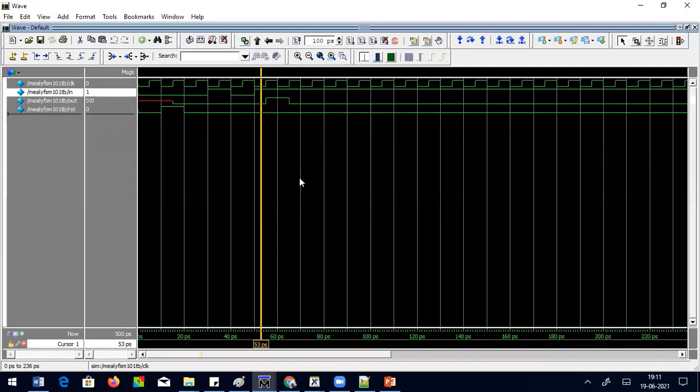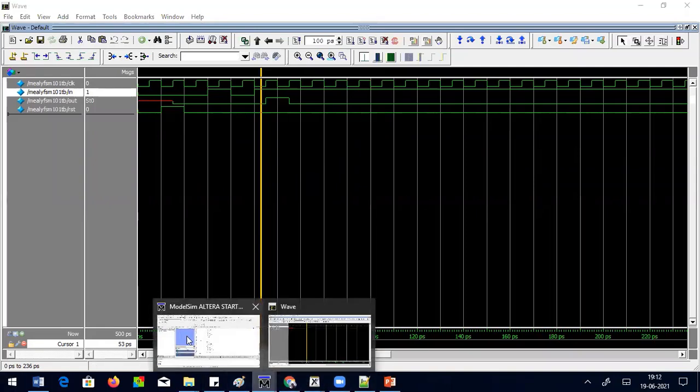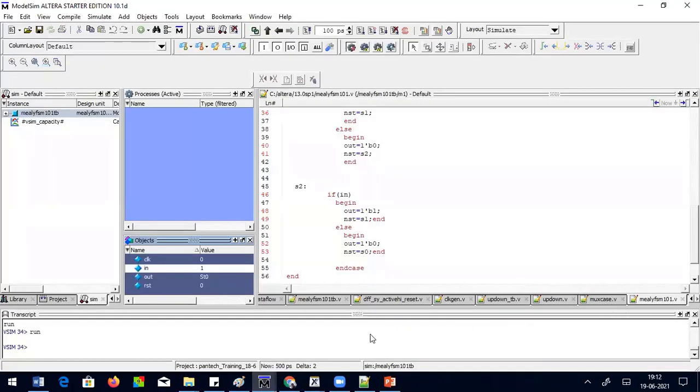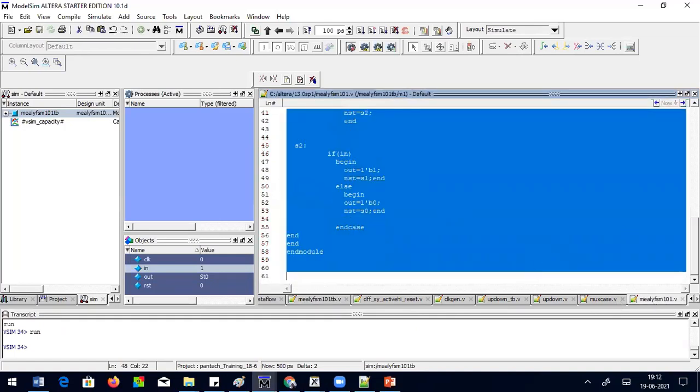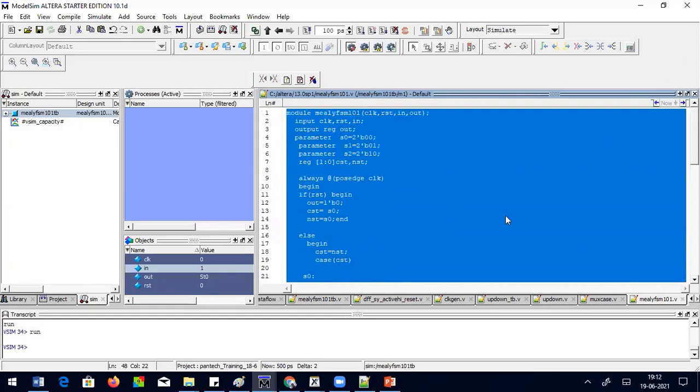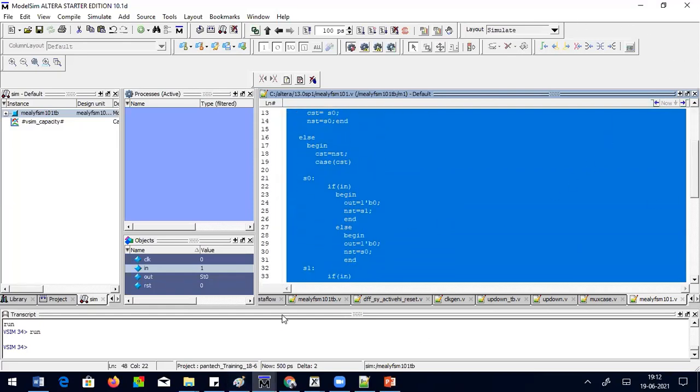The same thing could also be extended for Moore's machine. Only thing you need to change in the code, two things. Exactly the code will be the same except 2 points. Instead of 3 states, you will have 4 states. One more, in the definition of output, here you have defined the output after receiving the input, because Mealy machine gives their output after getting this input. But in Moore's machine, you should not give your output here. You comment here. Oh, I forgot to say this.